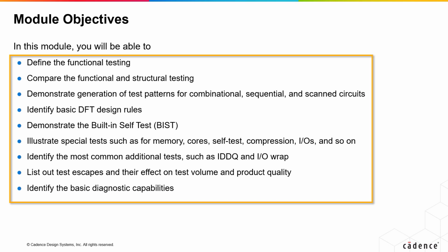Demonstrate the built-in self-test. Illustrate special tests such as for memory, cores, self-test, compression, IOs, etc. Identify the most common additional tests such as IDDQ and IO wrap tests. List out test escapes and their effect on test volume and product quality. Identify the basic diagnostic capabilities.